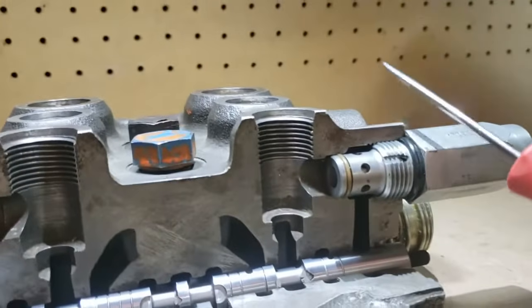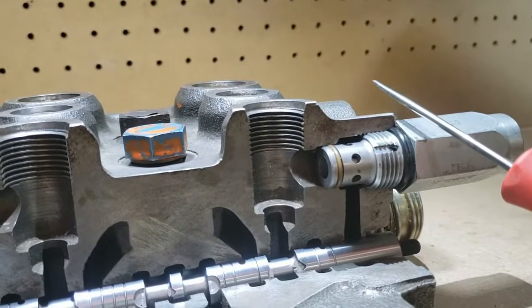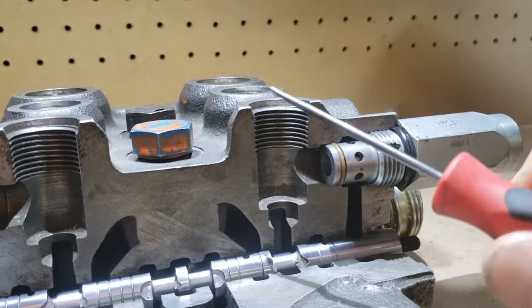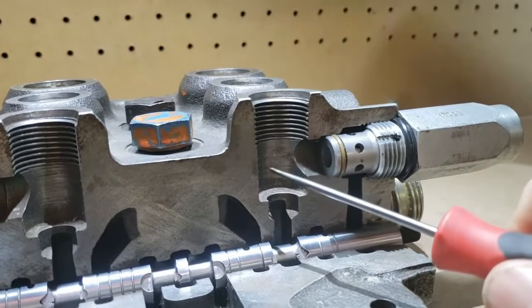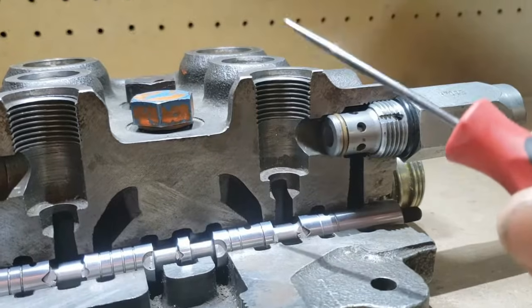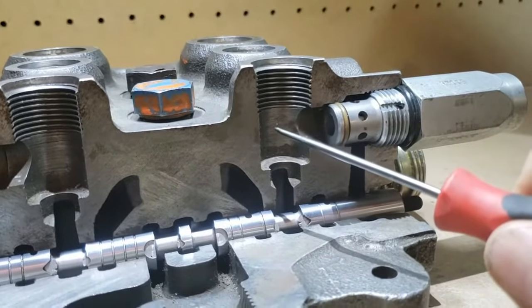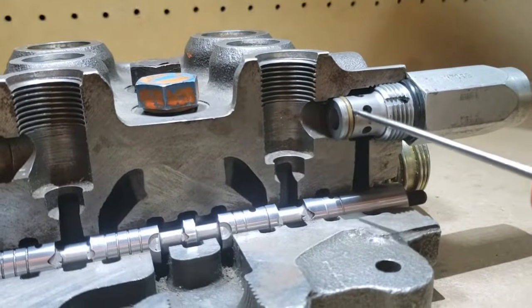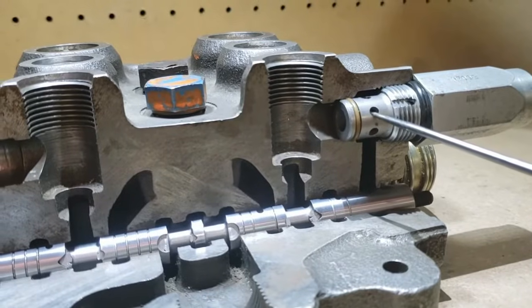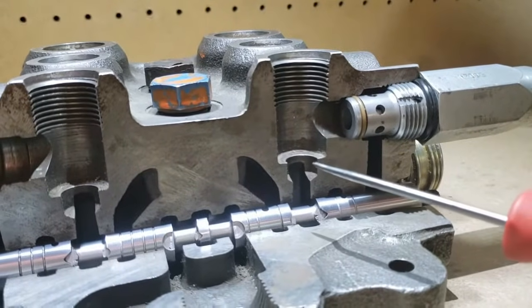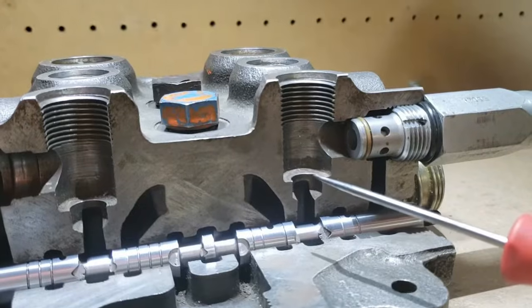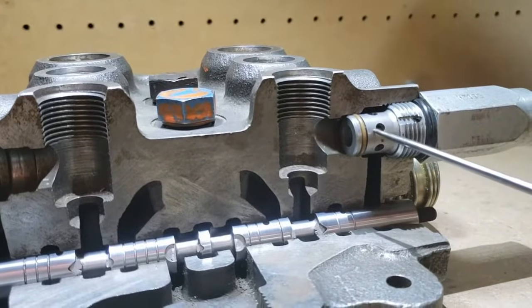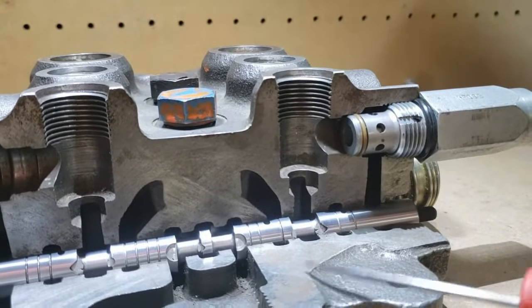The other time this relief valve might operate is if you park the machine outside on a hot sunny day and the oil starts to expand in the hose, and the charcoal gray painted cylinders start to heat up. That pressure could pop that relief valve open if the pressure in that trapped oil started to heat up and expand. So if it reached the 3,500 psi, it could pop open the relief valve instead